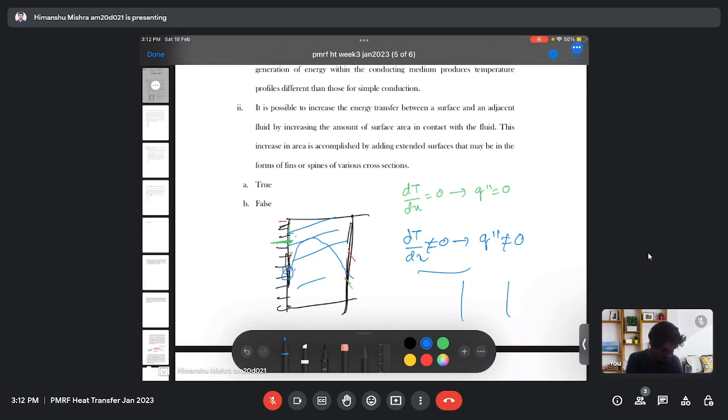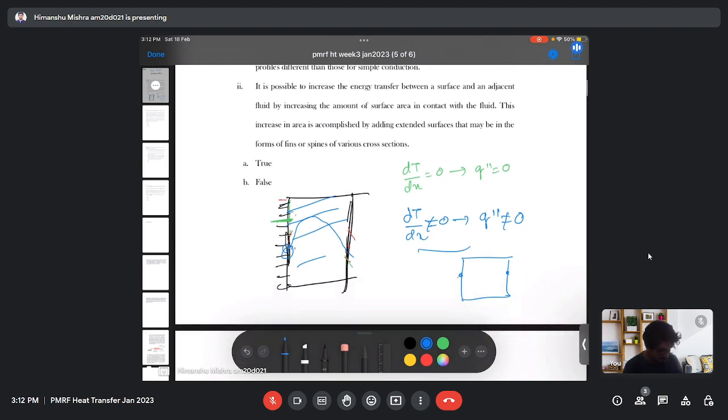For the plane slab, the variation of the temperature with heat generation depends on the boundary conditions which we specify at point 1 and at point 2. Based on the boundary conditions, the temperature gradient varies. In the first case, where one side is insulated, the temperature profile looks like the green line. But if the temperature at 1 and 2 is the same and there is heat transfer on both sides, then it would be perfectly symmetric. If it is different, then there will be some asymmetry in the temperature profile.